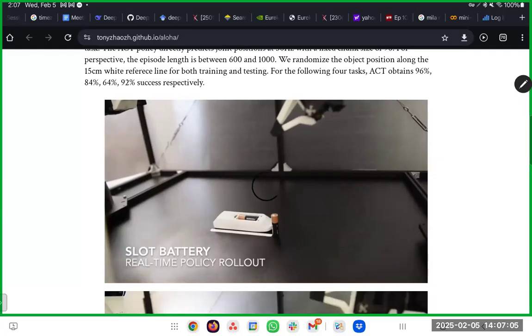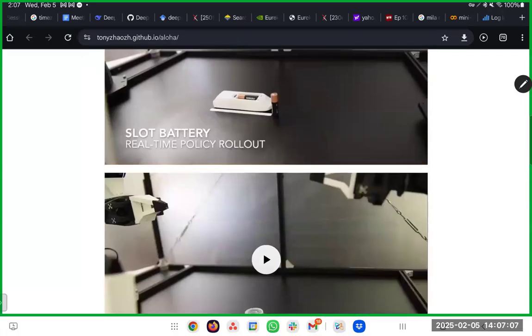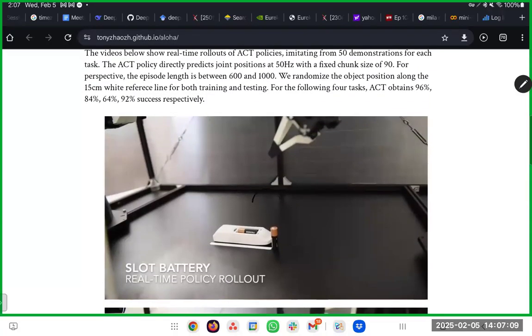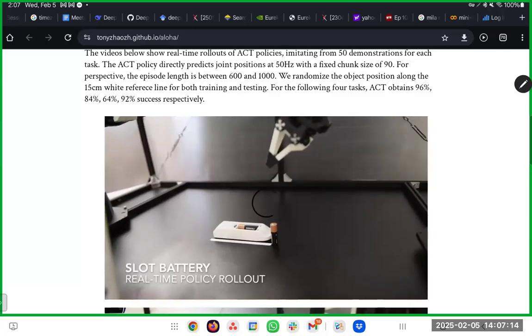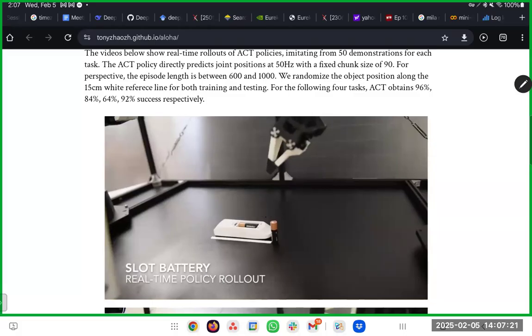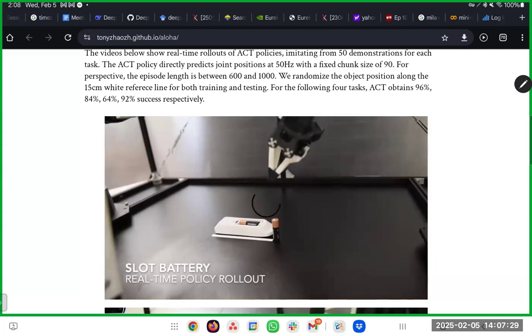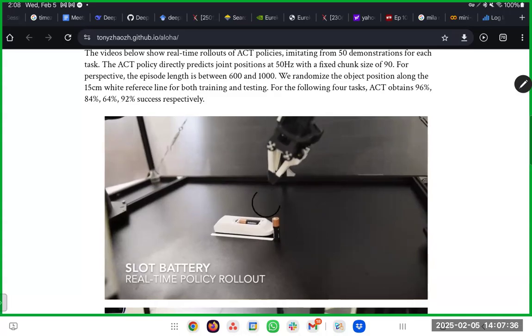So here, this is mimicry for these arms. I was trying to at least find a video for the haptic interface. Basically, there are these two controllers that are cylinders, and I think there's an extra switch for closing and opening the hand. When this robot hand reaches down and touches the table, the haptic interface that the person holds also prevents that device from moving any further down. So there's a much stronger connection between the physics at the end of the robot hand and what the person is actually sensing while collecting this data.